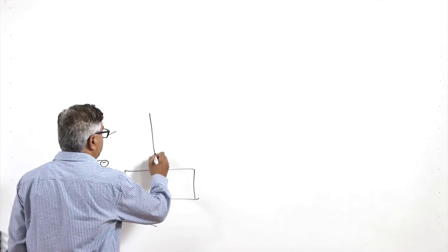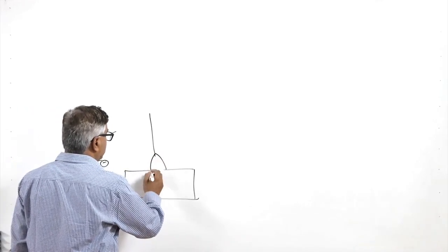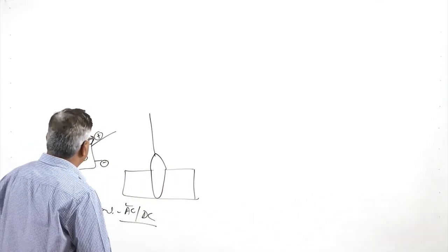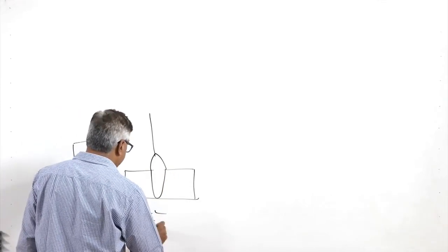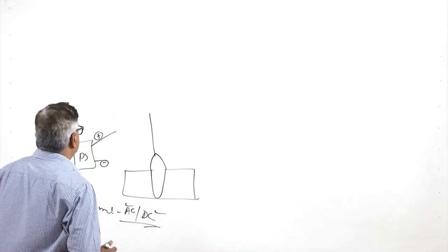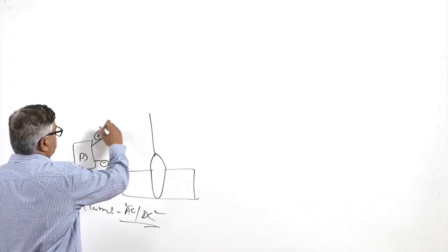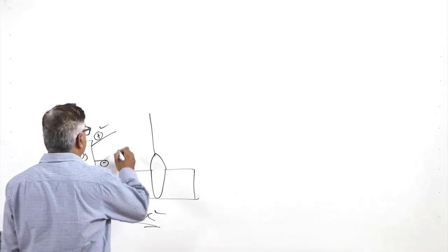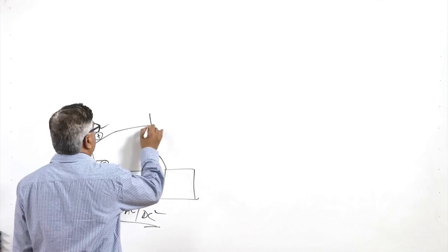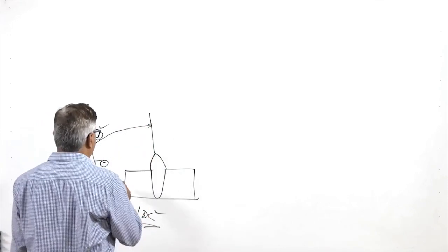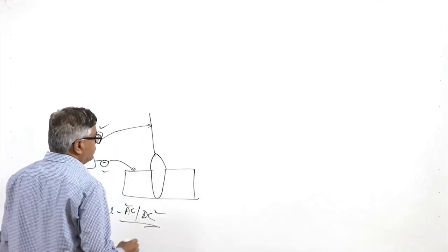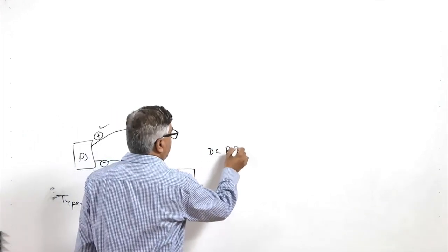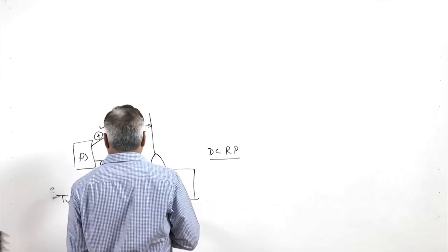Accordingly, the polarity of the welding arc will be changing, while in case of DC we have the freedom of choosing whether the electrode will be connected to the positive terminal or the negative terminal. When the electrode is connected to the positive terminal and the workpiece to the negative terminal, it is termed DC reverse polarity, or DC EP, electrode positive.